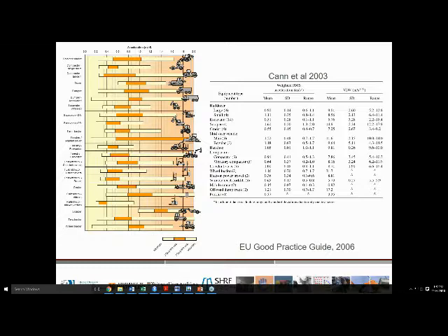Well, I guess in terms of vibration exposure, again, the key message: reduce your vibration as much as you can, and definitely use the current guideline thresholds as a targeted value, but knowing that there's still potential effects beyond that, or effects related to more acute sensory motor or cognitive changes. That's still a possibility at these levels. So reduce the vibration intensity as much as you can. That's the main takeaway.